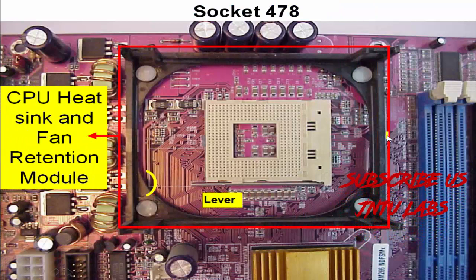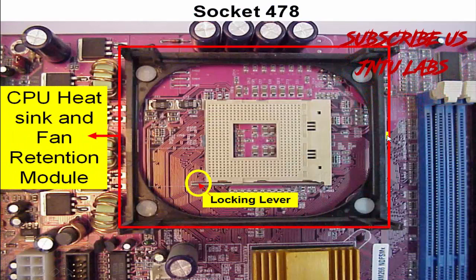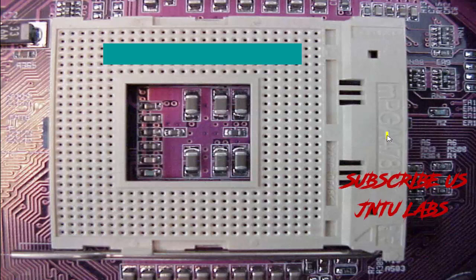Now we'll take a deeper look inside the socket 478, nothing but the CPU socket. The area in red is where we will be placing the CPU heatsink fan, which I have already told you about. The heatsink fan is placed on top, and you have a locking lever which is used to lock the CPU. The CPU chip we place on that and then lock it. The locking lever is very important. We should be very careful while we place our CPU, because the CPU, your processor, can be damaged.